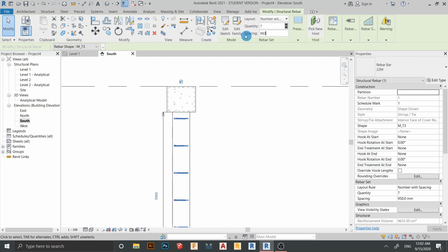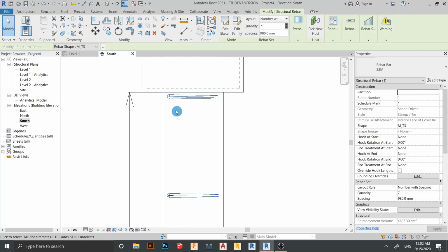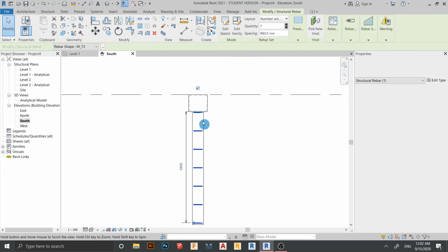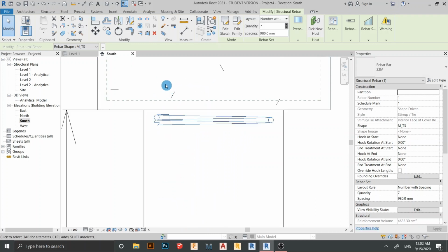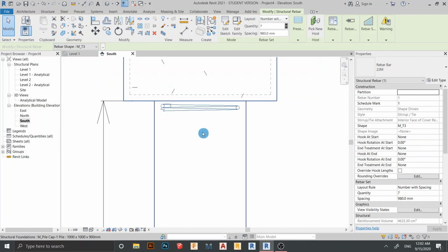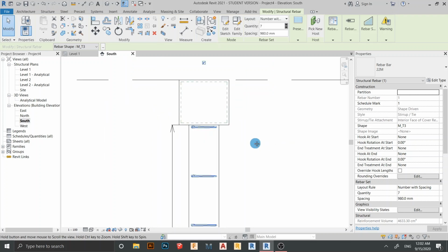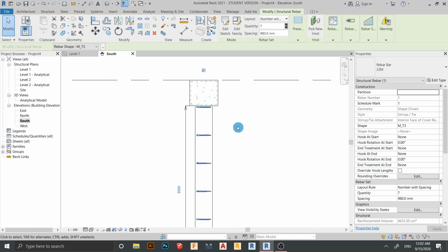Okay, this one I'm changing to something like this. Okay, it's perfect. So I'm going to add another rebar here, but it will be smaller than our cover because I don't want my rebar to overlap later on, because this time we add another rebar here, a lot more than before. I think around 50 or 40, and this one I just give you as a quick example for creating reinforcement in a pipe cap in Revit. I have one calculated. Normally we need a structural engineer to calculate first before we can run our rebar in our pipe cap.